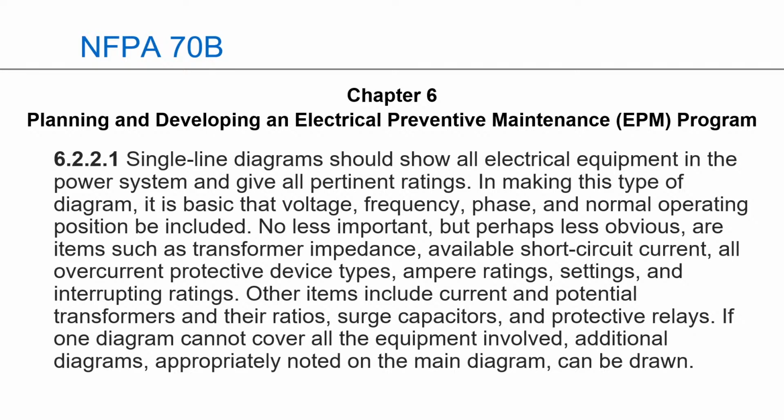The voltage, frequency, phase, and normal operating positions should be included. No less important, but perhaps less obvious, are items such as transformer impedance, available short circuit currents, all overcurrent protective device types, ampere ratings, settings, interrupting rating.